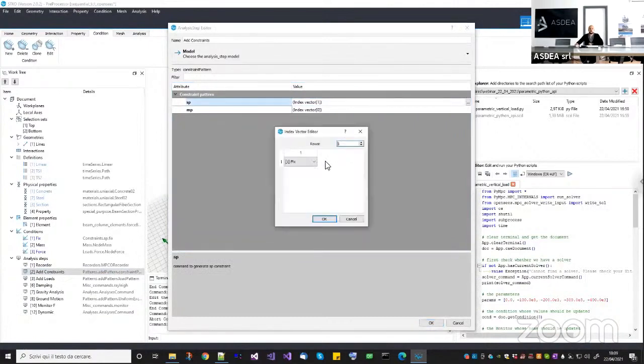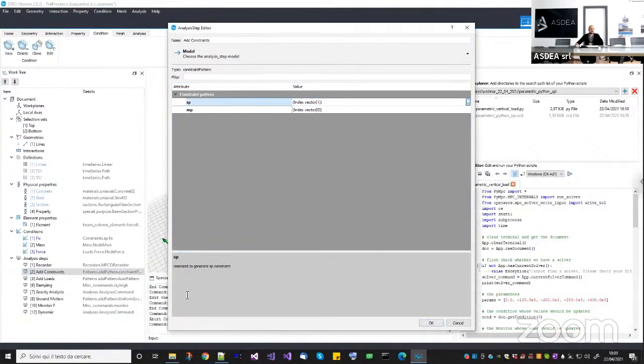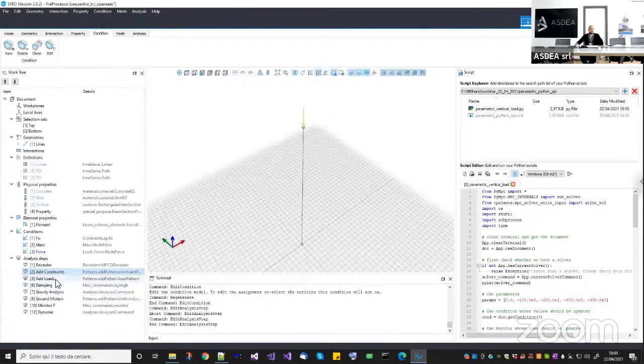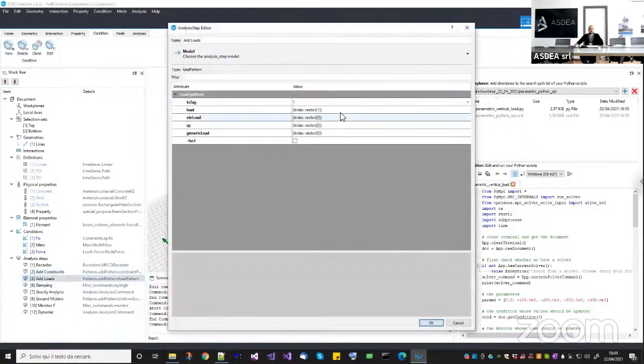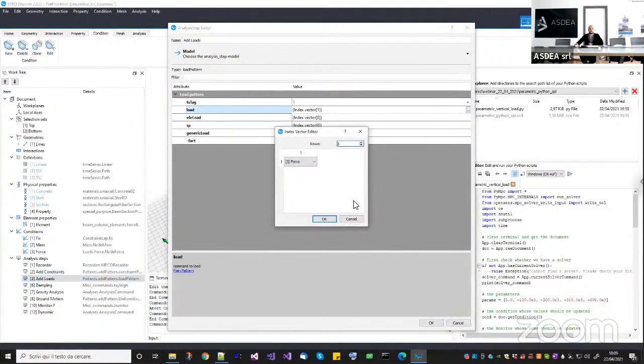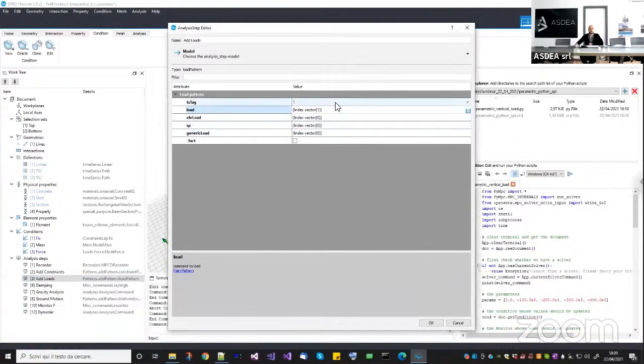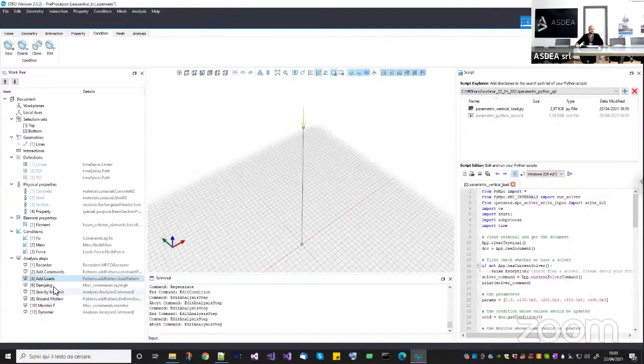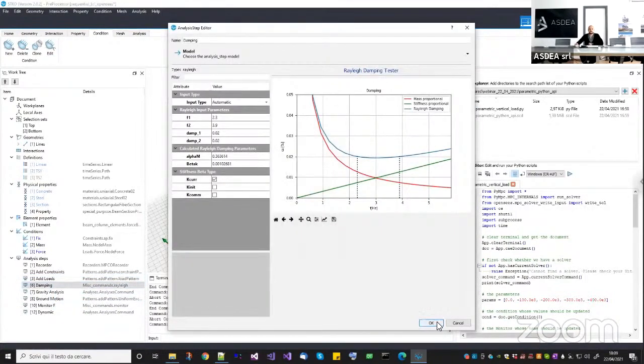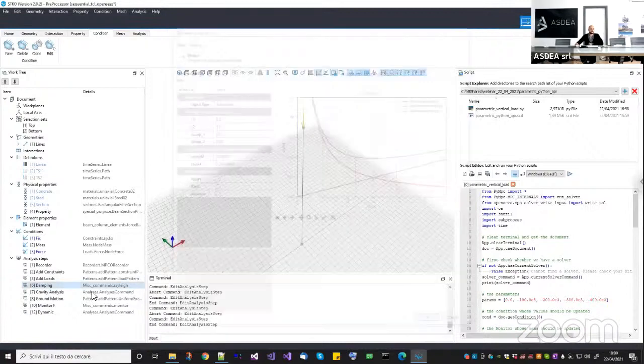And we just have a fix at the bottom, so nothing special. Then we have vertical loads, okay? So the single vertical load that we have here associated with the linear time series, right? Then after this we define the damping. Damping can be defined here or later on before the dynamic analysis, it's not important.